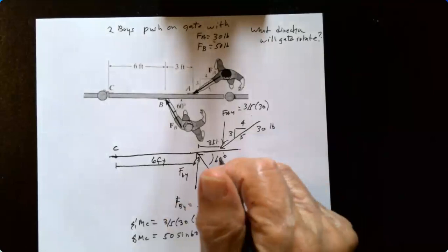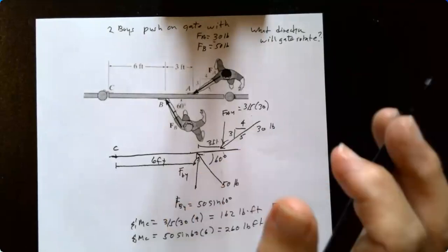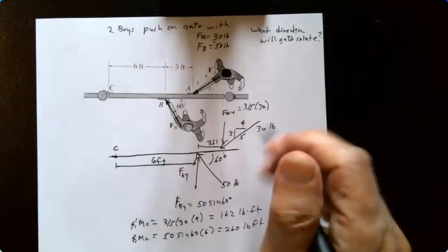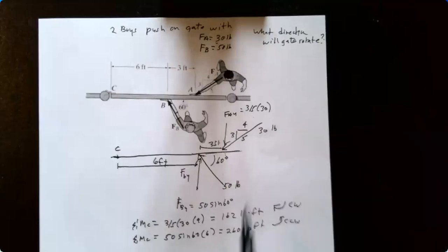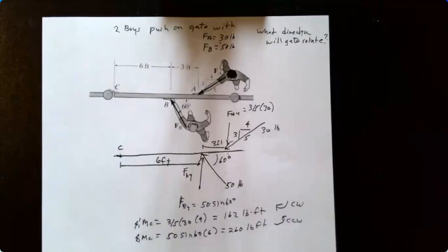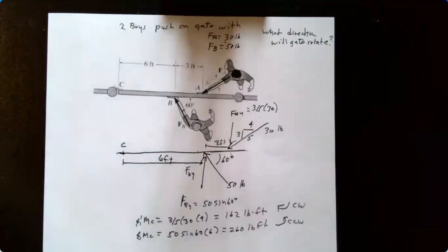Find an angle that would keep this in equilibrium. Okay. So you can do an angle or you could do a force, choose either force, and so you can make a couple of different problems out of this. In that case, you would sum moments equal to 0 to solve for your unknown as you go through that.